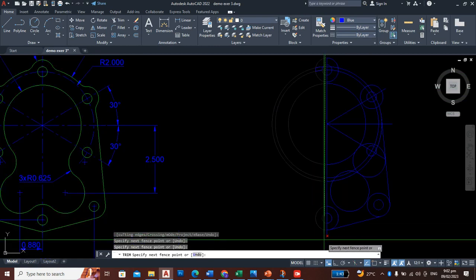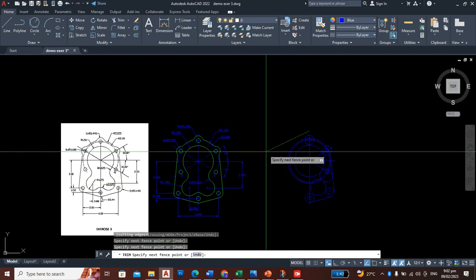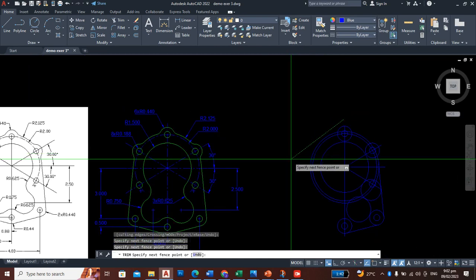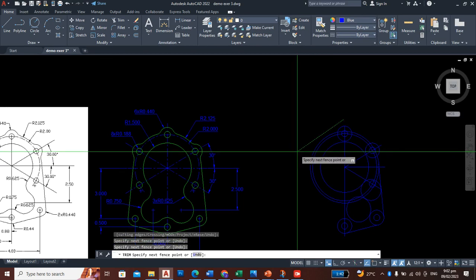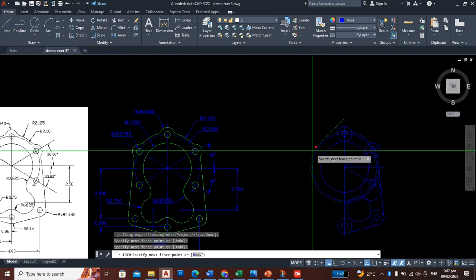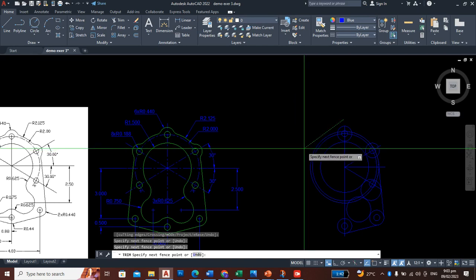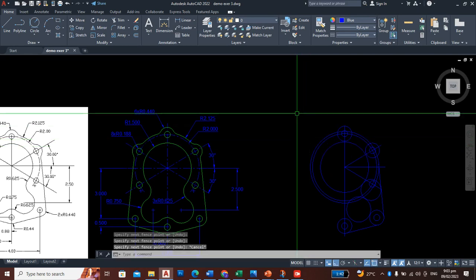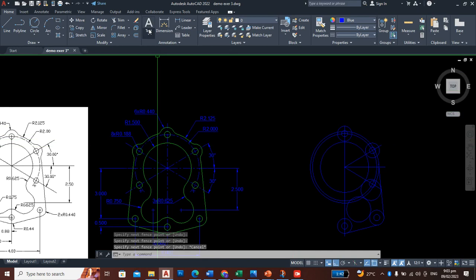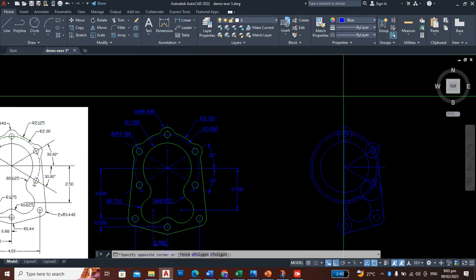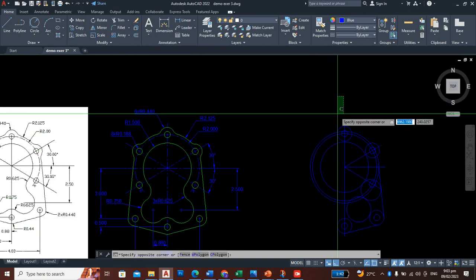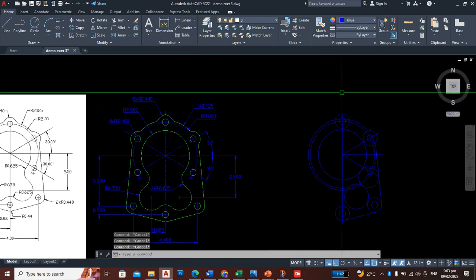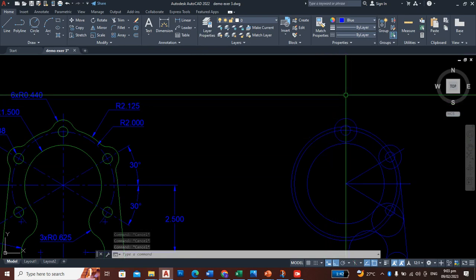But in lower versions, let's say 2014, you still need another option to complete the trim action. The quicker one is like this. In newer versions, immediately you can trim and do crossing selection, not clicking one by one. It's very slow.